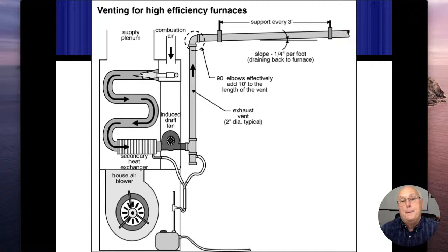All right. But since I'm absorbing 95% of the heat, and only 5,000 BTUs are going out the vent, that change in temperature is so drastic that it pulls a lot of moisture and condensation out of the air. Hence, that's why they get the name of a condensing furnace. I have no choice. I have to be able to collect that condensation, and I have to give that condensation a place to drain. In our area, we pretty much go with gravity drains.